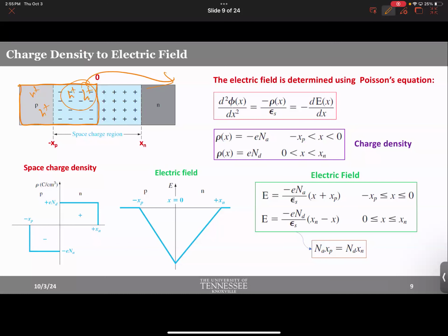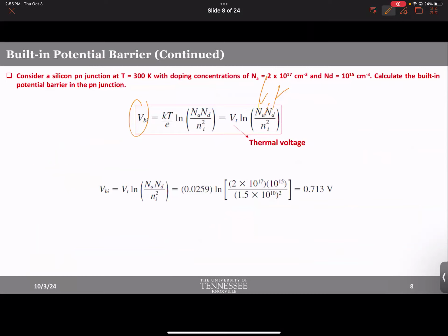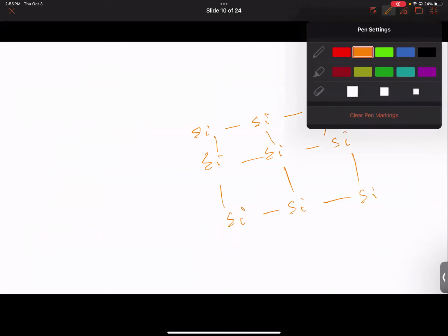So holes came from what? Came from the dopants. Basically, dopants led to holes, and dopants led to additional electrons, right? Remember I told you this? So when the holes leave, they leave behind fixed charges. Like, for example, in silicon, silicon, silicon, silicon, silicon, silicon, silicon. Imagine in this situation, there is no free electron or no free holes.